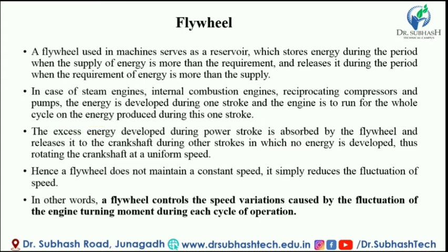So the excess energy developed during the power stroke is absorbed by the flywheel and released into the crankshaft during the other strokes, in which no energy is developed. Thus the crankshaft rotates at a uniform speed.